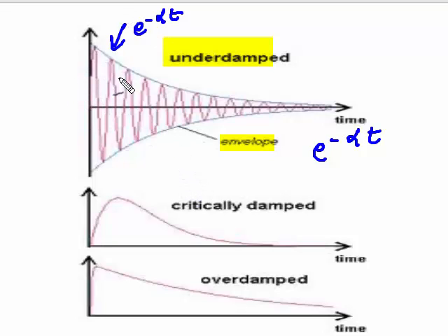And here are the oscillations that are coming on in between, and they're asymptotically approaching 0 in the underdamped case. For the overdamped case, there are no oscillations. It's just going towards 0. In the critically damped case, start with a cosine term. You might see it go underneath, come back up, maybe not even quite that. And here it's a sine wave, so you see it starting to make one oscillation and then damp out. So here's your critically damped case, overdamped, and your underdamped case.